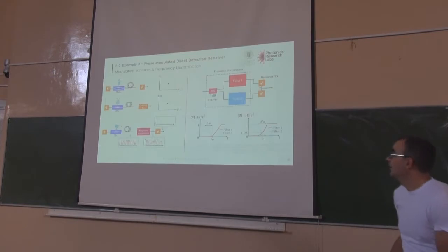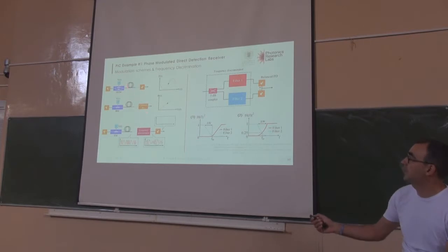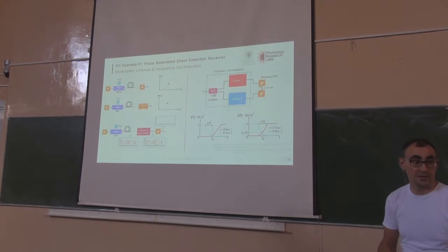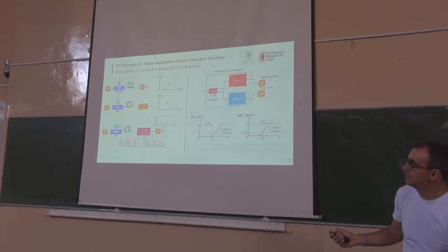Okay. There are different means of transmitting a microwave signal through an optical fiber network, but all of them need modulation, either amplitude modulation, phase modulation, or equivalently frequency modulation, right? If you do amplitude modulation, you can use a single detector, okay? If you use a phase modulation, maybe you can use a coherent receiver that we saw yesterday with another laser, etc. And if you do frequency modulation, like this one, lower frequency, higher frequency, you can use a discriminator, okay?